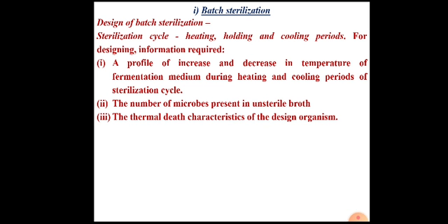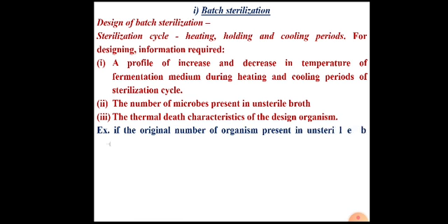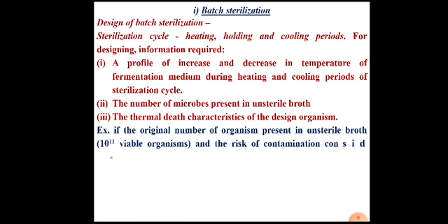So the death characteristics of that Bacillus stearothermophilus, that is the thermal death curve, meaning its K value, the specific death rate, at different temperatures, at 121 degrees Celsius, at 125 degrees Celsius, at 130 degrees Celsius, etc., has to be known. If we know these three, then designing of batch sterilization is possible.